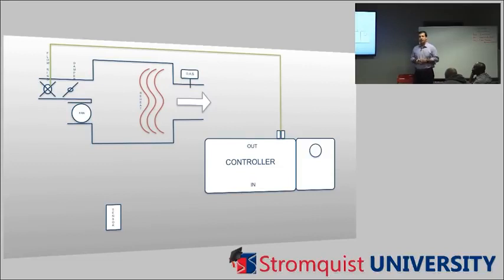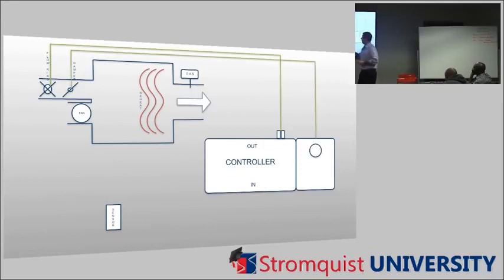So think about it for a second. Output, you got it. Now why is it an output? Good job, whoever said that. It is going to be an output because, well, I'm giving away the next one, but the sensor is giving the controller the signal of what's going on in the space, and then the controller sends that output to the damper to tell it to open or close, modulate, however I need it to be.